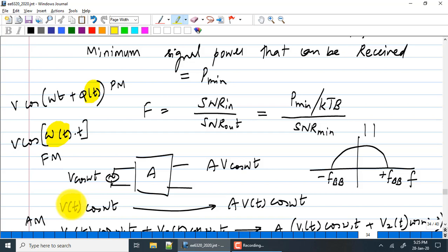Right? What you do is, in the digital domain, you perform PM, FM or AM and then convert that to analog using a DAC. Right? If you look at the DAC output, of course the information is contained in the amplitude, phase or frequency, but you will not be able to directly demodulate it until you use the analog to digital converter at the end of the receiver chip and then apply appropriate demodulation techniques in the digital domain. Does that make sense? I hope it does. For now it will have to do. Okay. Otherwise we will now be not doing nonlinearity but something else.